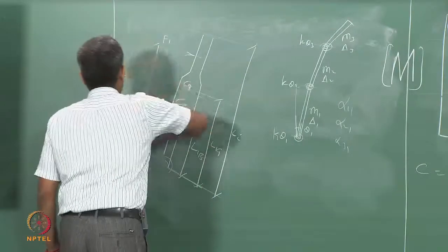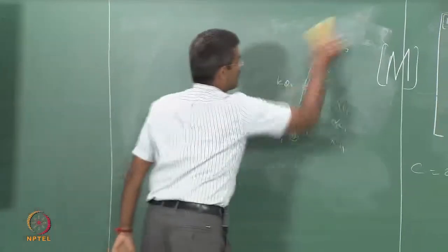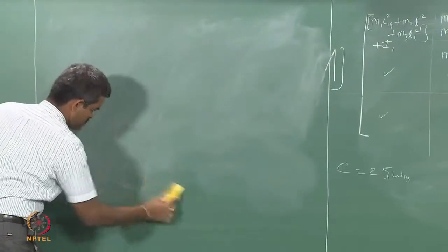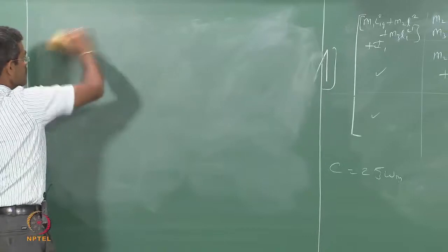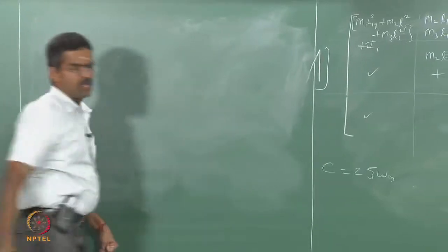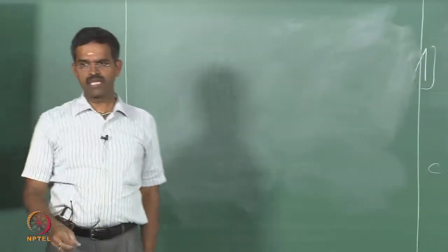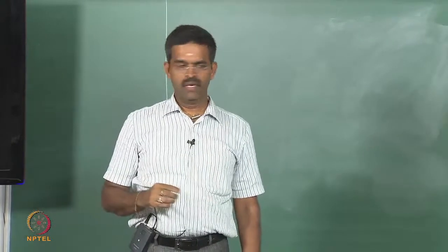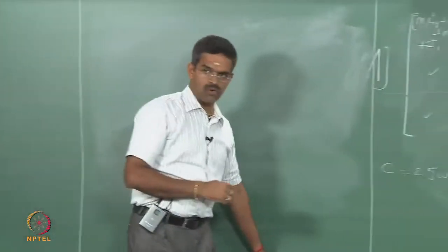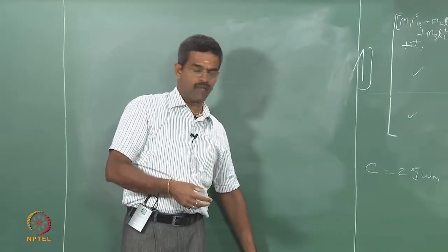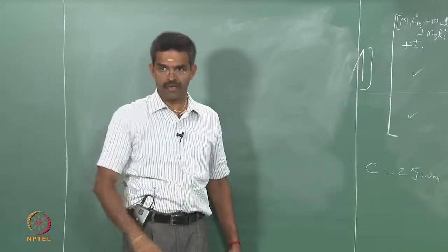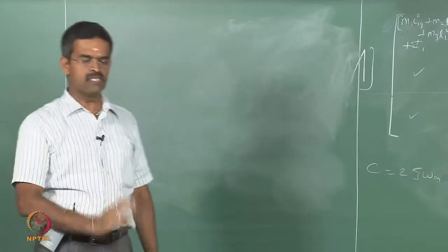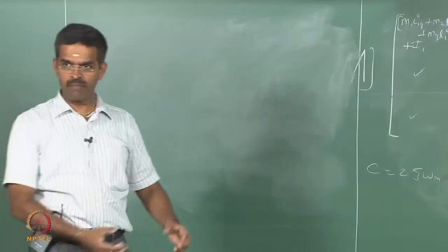So in the last lecture we appreciated that for deep waters, from shallow to medium depth, offshore platform designs have been formulated to have a compliancy introduced in the design. The compliancy introduction will also cause increased flexibility. Therefore, the system should have a recentering capability. When the system is pushed by a lateral force, there should be a recentering element in the system which will try to bring it back.